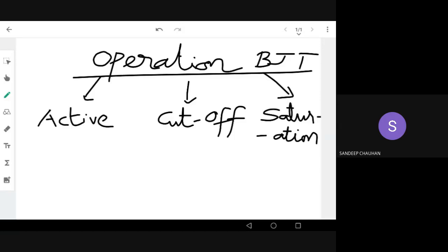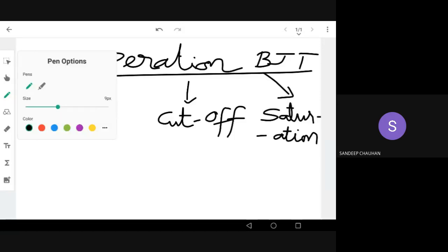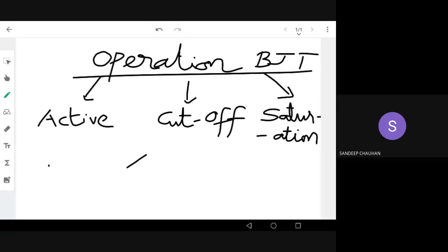So we have already drawn the transistor. Let me also draw the symbols of the transistor. So this is the transistor. I already discussed one day how to find the terminals and which type of transistor you're using. So you can see the arrow. This arrow denotes the current direction. So we know the current direction. Current always flows from the P to N region, right? So we have to know this arrow is from P region to N region, right? So the last region will be N only, definitely. So this is an NPN transistor, right? So again, we have another type of transistor, something like this.